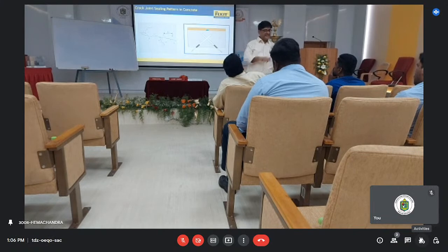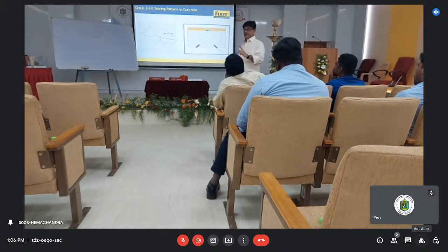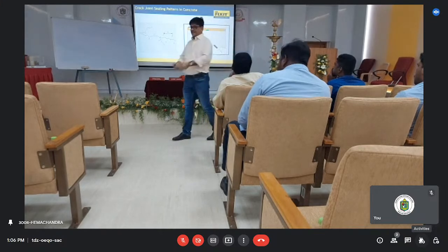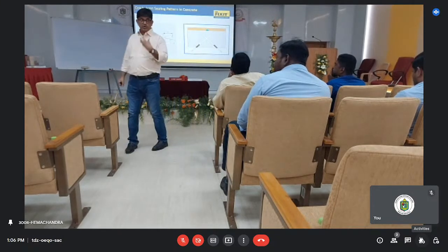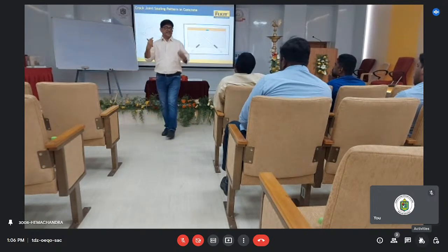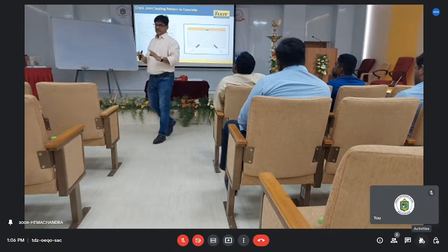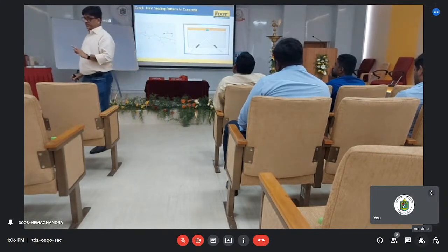Sometimes what happens is the area you break is not that much, and the material will also give a back pressure. Grouting is a very serious operation. Safety is a must for it. When people think of grouting, it can actually create a bounce back. Specifically in the case of epoxy injection, the whole concrete can bounce back. Please take safety, always take safety.